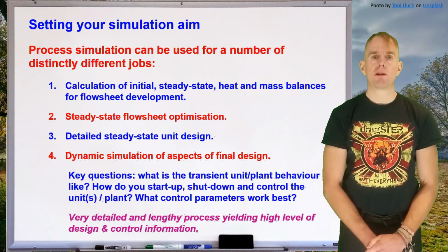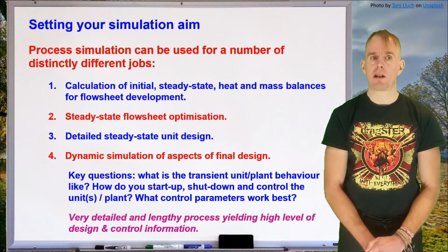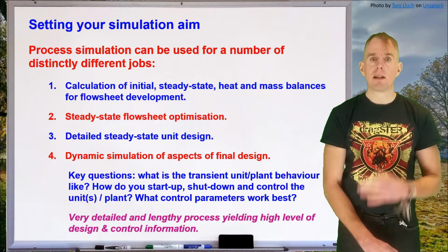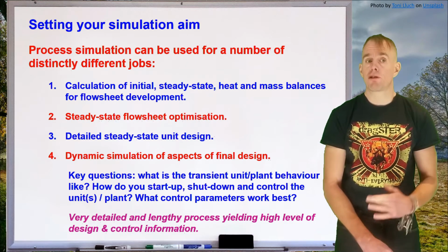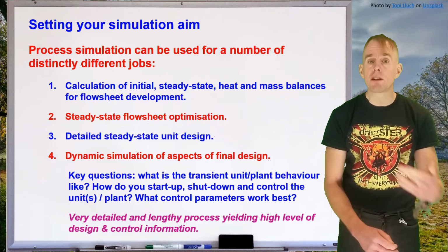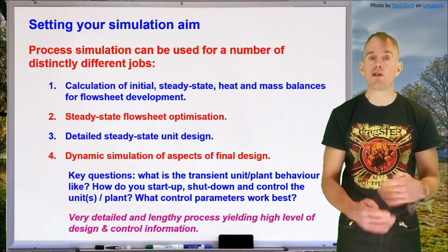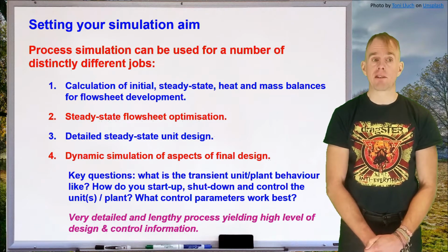Now, the fourth job you might wish to do with a process simulator is look at the dynamic simulation of aspects of the final design. The key questions here are somewhat different. It might be, for example, what's the transient unit behaviour or the transient plant behaviour? How do you start the plant up? How do you shut it down? How do you control certain units? What control parameters actually work best?